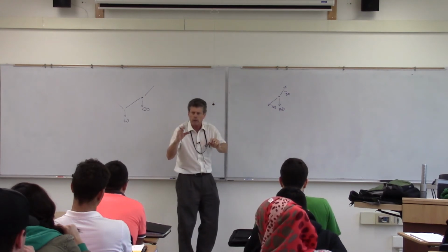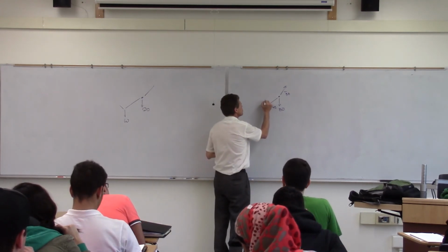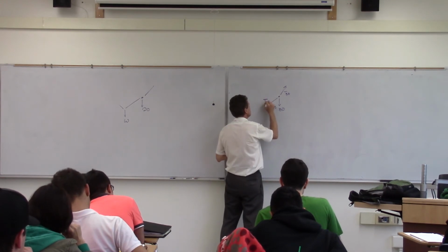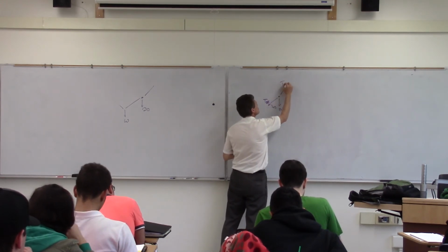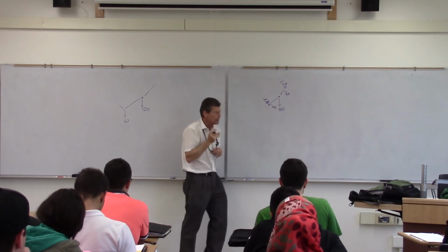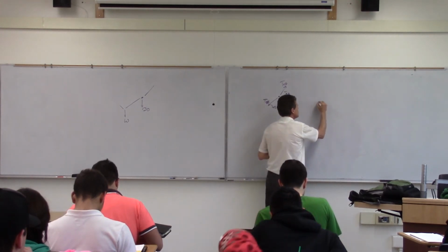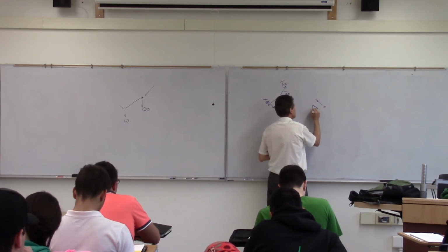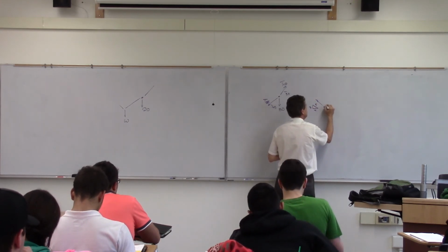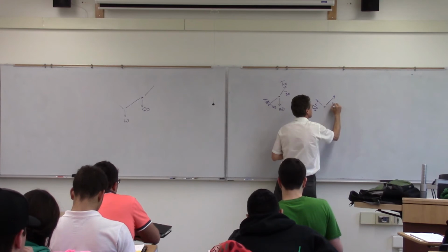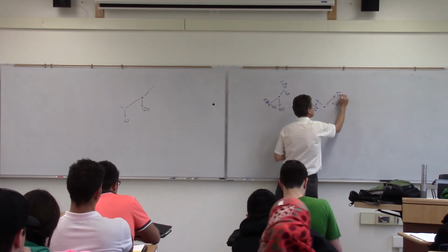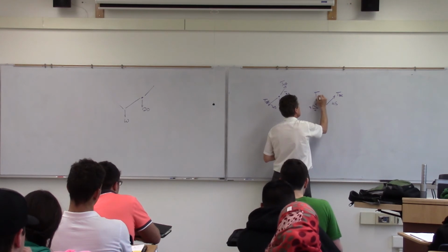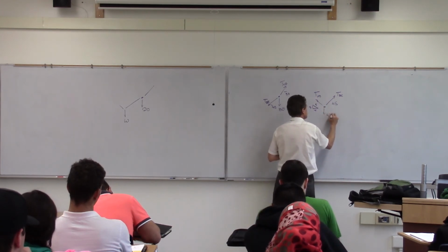But the key thing is we can solve for this force, which was TCD, I think. Or no, this is BC. This was TCD. Once we solve for that one, then we can come back to this one, which was everybody's favorite, the 3, 4, 5 triangle. And this was at 45 degrees. So this was TBC and TAB, and then our unknown W.